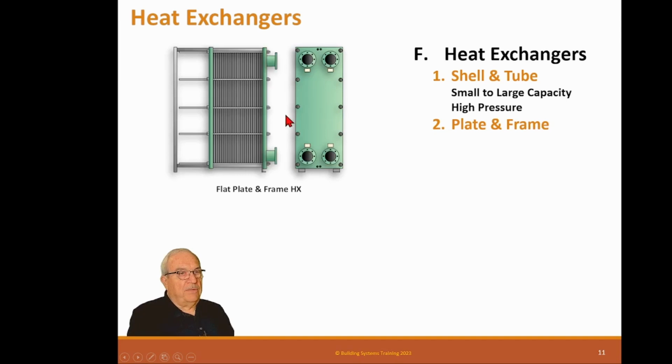Then there are plate and frame heat exchangers, which basically have plates with grooves on them. What happens is these grooves direct the water so that the water runs like this down to the outlet, and then the process water runs this way down to the outlet, and they transfer heat through these stainless steel plates. These are low pressure, very efficient, but they won't take really high pressure because these are designed to be cleaned. These were originally designed to be pasteurizers in dairies for milk. So every day they had to take them apart and clean them.